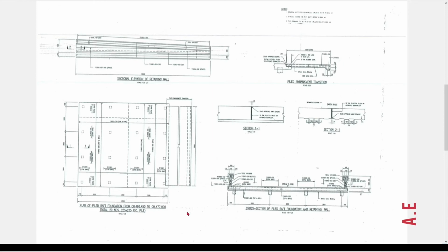At the interface where normal embankment meets the pile embankment, a transition slab is also proposed to avoid localized settlement of the embankment. Another main function of this transition slab is to provide smooth riding conditions for road users, as the change from flexible embankment to rigid embankment zone will create harm to the drivers.